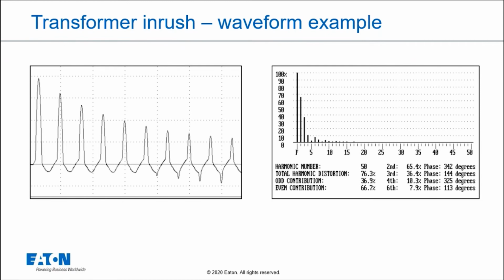It's interesting, but when we look at characteristic waveforms for loads like this that produce second, third, fourth, fifth, those even harmonics, a lot of times we end up seeing something that looks a little different in terms of waveform. But again, this is a short-term waveform that we see with transformer inrush.